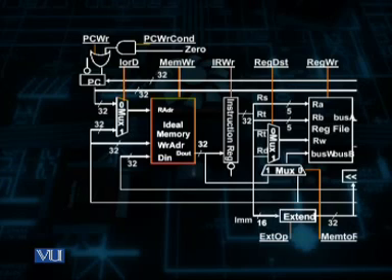Clock cycle 2 is basically used for instruction decode. However, as we discussed in the single cycle case also, instruction decode takes minimum time, since it is done with the help of a decoder circuit, which is a combinational logic circuit, and usually the time required is equal to the propagation delay of the gates used in the instruction decoder.